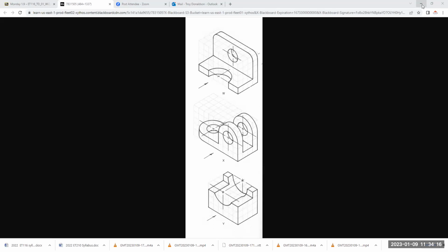Because if you're in paper, watch, the scale goes away, because scale doesn't make sense in paper space. In model space, scale's here, and I can choose one. And if you use the roller mouse, it's just some random scale, right? But if you choose one of the engineering scales, we're going to just stay with those for now.